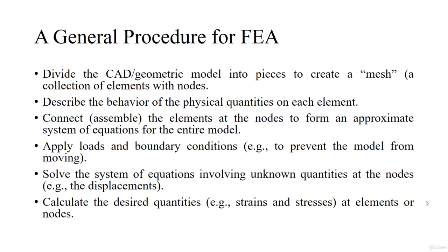In this lecture I am going to tell you about the general procedure that is adopted for solving a finite element problem manually, and then we are going to see what is the procedure adopted for solving a problem using FEA software in the industry. So the first and foremost procedure for solving these FEA problems manually is you need to divide or convert the CAD or geometric model into pieces, say mesh.